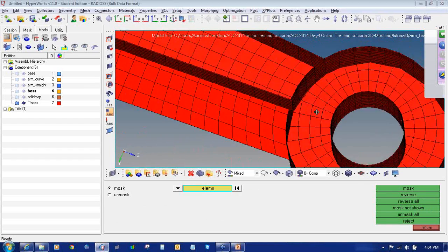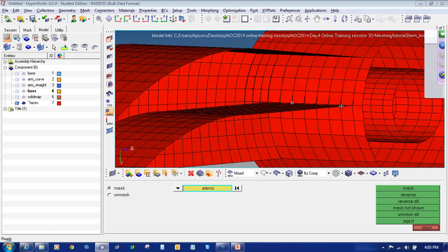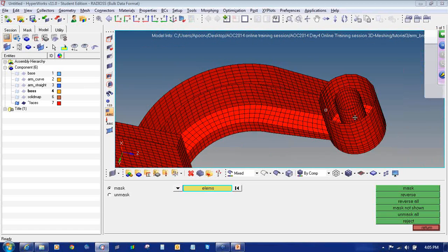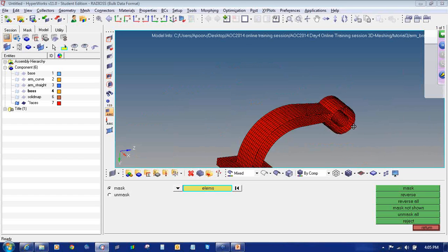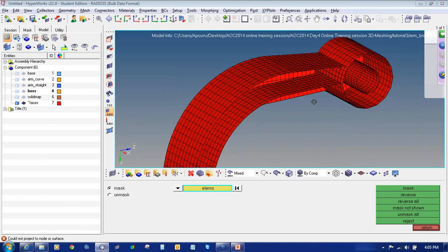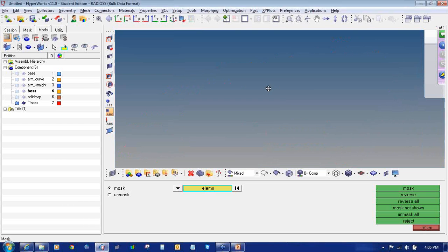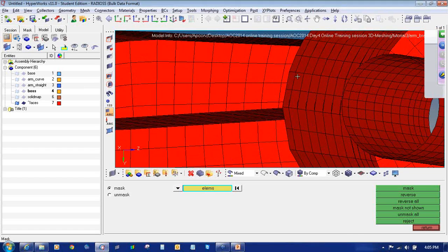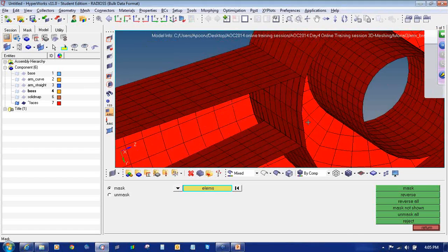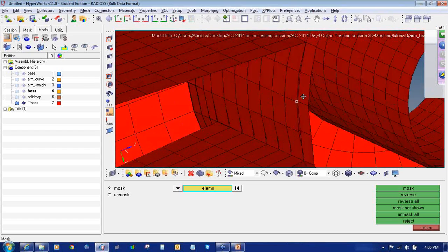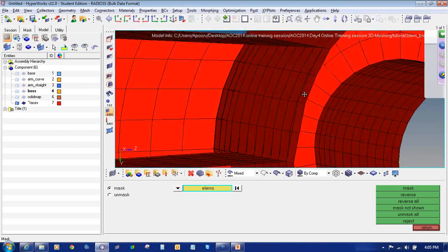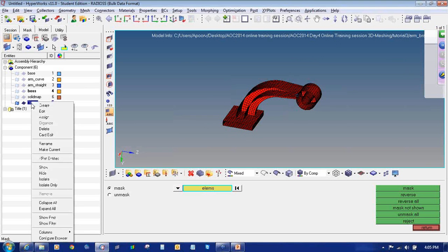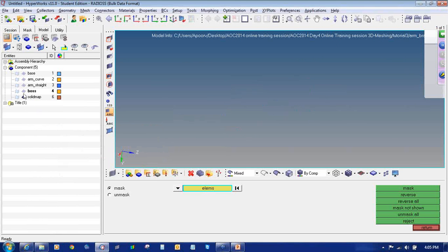It is giving two faces. You can see here. So it should not show like this, it should not create faces like this, it should be hollow throughout. You can see in this portion it is providing two faces, here you can see. So how to solve them? So I will again go to delete, right click on delete this,